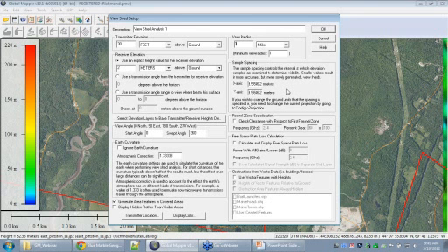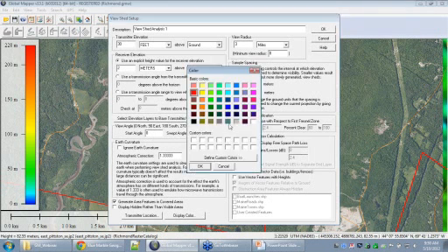Mine is about 10 meters, and that's going to be fair for the purpose that I'm doing here of this small area. And there's, again, those other options. In this case, I'm doing a visual line of sight, so we can actually ignore some of those settings like the Fresnel zone clearance and such. If we're going to do multiples of these, there is a display color.